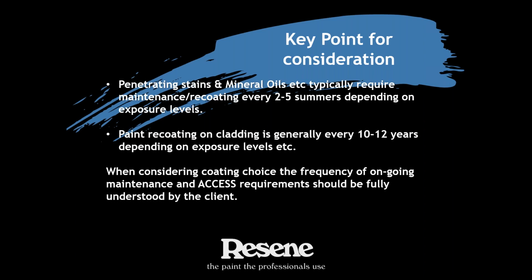So key point for consideration on this one, and this is the thing we talk about a lot on the phones, we get asked, well, what's the difference between stains and paints? And the key points are: stains and mineral oils require maintenance every 2 to 5 summers, depending on their exposure levels. When we say maintenance, we're talking recoating, restaining, sorry.